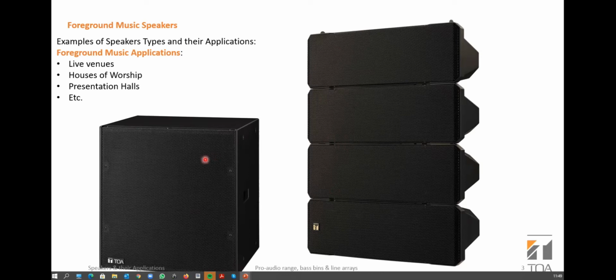And you use thicker grade. We normally use thicker grade oxygen-free cables for our installations with PA systems. And these cables must be short, preferably within 10 meters from the amplifier to the speaker. If you are rocking serious music and you touch that cable after a while, it warms up because it pushes a lot of heavy current into the speakers.